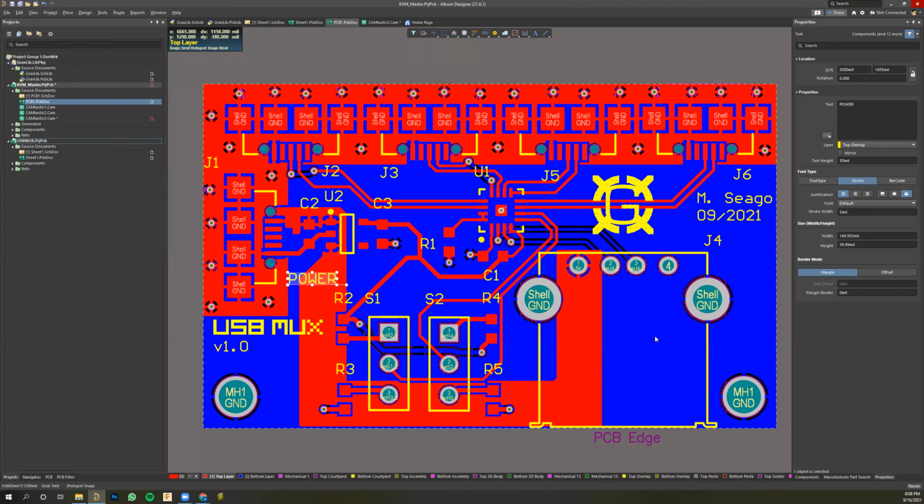Test points can take any form. Y'all are familiar with the pin header, the type of pins that match breadboard spacing. If you had I2C lines, you could put a 2-pin header and break out the I2C lines, and so you could connect to them. There's a bunch of other types of test points. You can define a test point however you want.